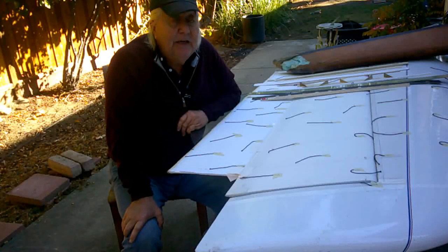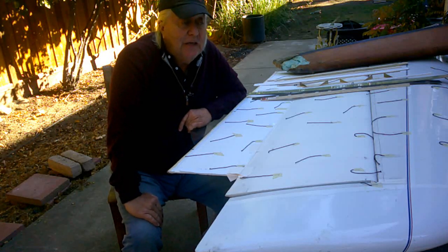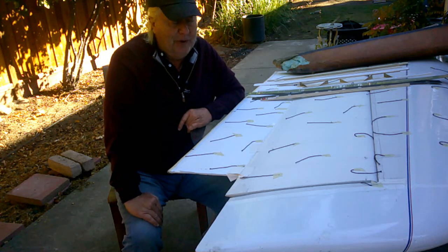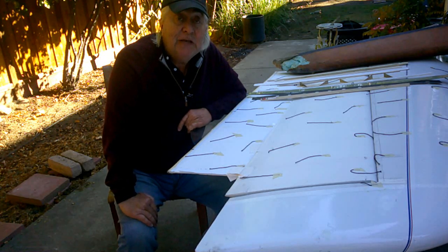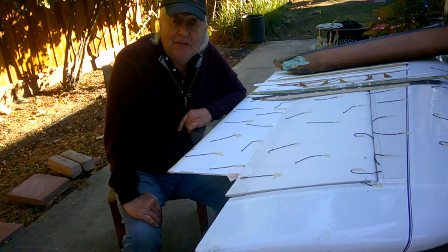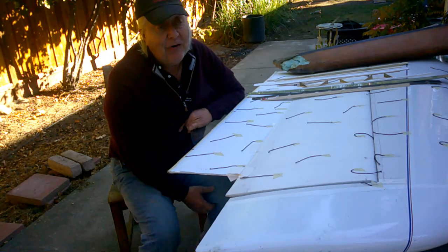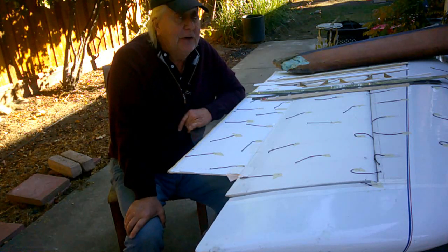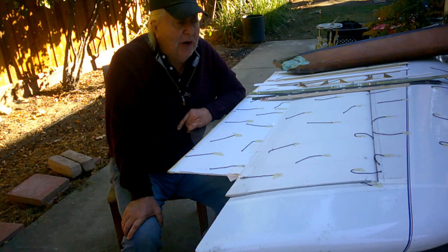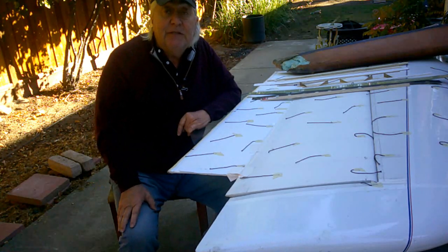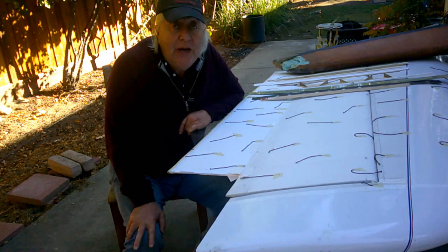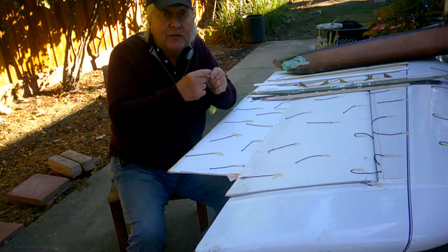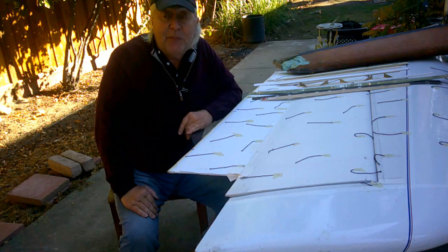And another factor that was involved here is I wanted a wing with superior performance. We were aiming for an L over D of 30 to 1 or better. Usually in designing gliders, you can consistently get a higher L over D by increasing your aspect ratio. Now, the aspect ratio is simply the span squared, tip to tip, divided by the wing area. So there's two ways to increase your aspect ratio: reduce the wing area, so a skinny wing, or increase the span.